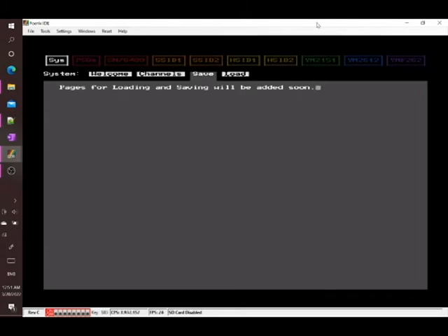Speaking of the Discord, someone there mentioned that I might also want to use MIDI system-exclusive messages. Those are useful for sending custom messages, but they're a little slower because even though they're variable in length, even at a minimum they contain a few more bytes than the standard messages. Even so, I might allow the user to send sysex messages to reassign parameters to MIDI controllers mid-piece, or maybe even rearrange the channel assignments, because it would be great to be able to change which chips you're using in the middle of a piece. But none of that is implemented yet.